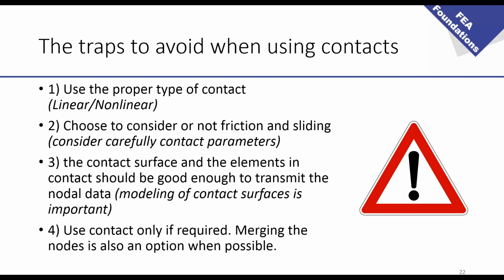The third thing is that the contact surface and the elements in contact should be good enough to transmit the nodal data. So in some cases when your model is very complex, be sure that the contact surface is meshed sufficiently small and well enough that the contact will be transmitted correctly.